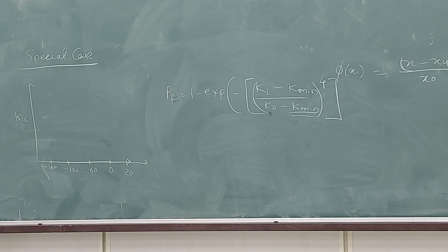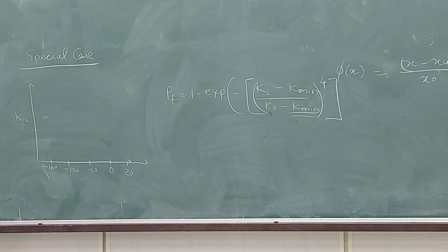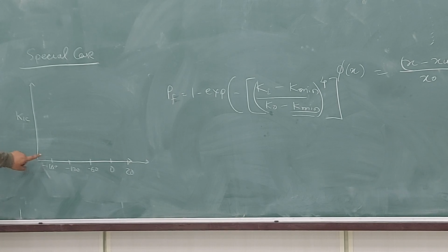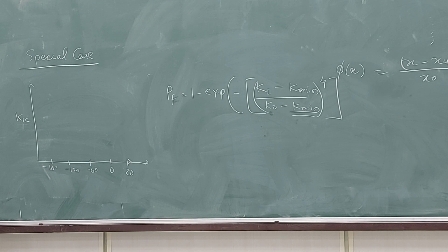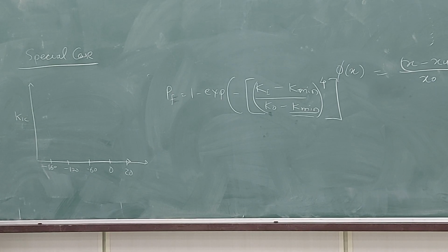Increase. Don't look at the equation. Think about the reality. It's a BCC material. It's a steel, ferritic steel. Okay? Increase. And so you are doing testing at different temperatures. Right? So as temperature increases, ductility increases, you should think that the toughness will increase. Right? Or wrong? It will increase.